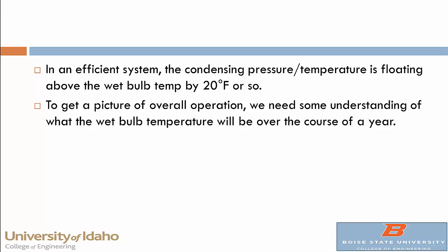So for a given amount of heat, a certain delta T is good enough to drive our heat transfer process. That means as it gets cooler outside, the temperature of the refrigerant in the condenser can also cool down. And what that means is it doesn't have to be as high a pressure, and lower pressure takes less energy to achieve. So that's the core of the energy efficiency opportunity, and why we're looking at this is that we want to be able to allow the facility to control their system so that discharge pressure isn't always at a constant value.